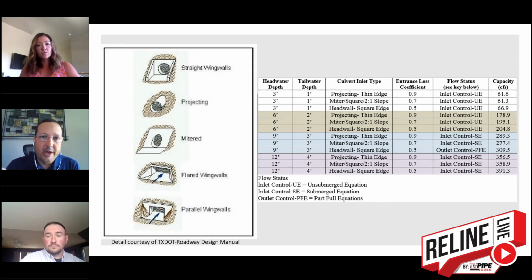The issue is that we have a limitation on manufacturing with the HydroBell, so we only go up to the 63-inch size that matches the Snap-Tite. It's typically going to work well with inserting into a female end of Snap-Tite. When we don't have that option, we're working with profile pipes that are bigger. Then we move to the other options, such as a reducer that is still available, but not as preferred as, say, the HydroBell. That's a good question, though.